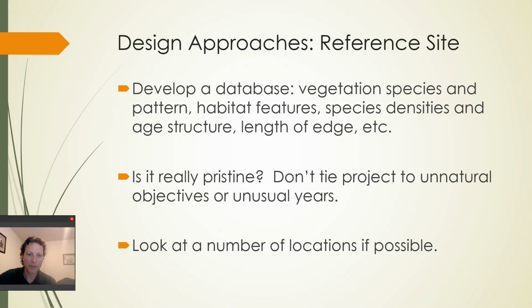And you come back the next year and the reference site is bone dry, that it's actually an ephemeral stream, not a year-round stream. So that's just an example of needing to really survey the local community about the place, looking for data that already exists, or watching a site over a number of years to make sure that you understand how it functions.